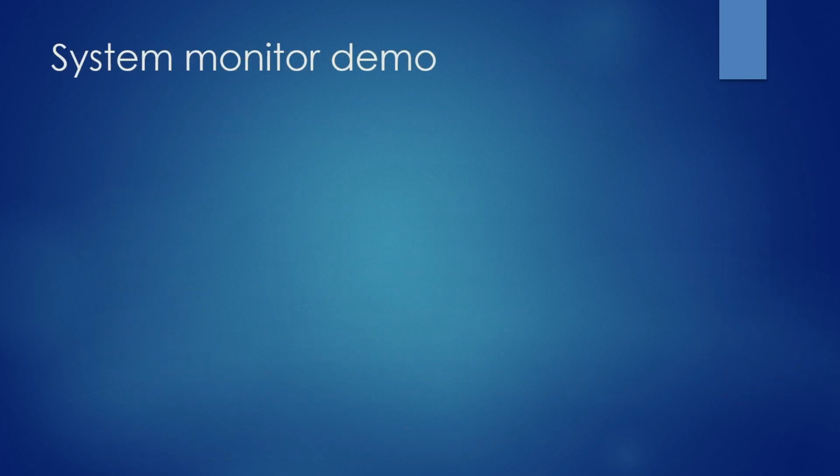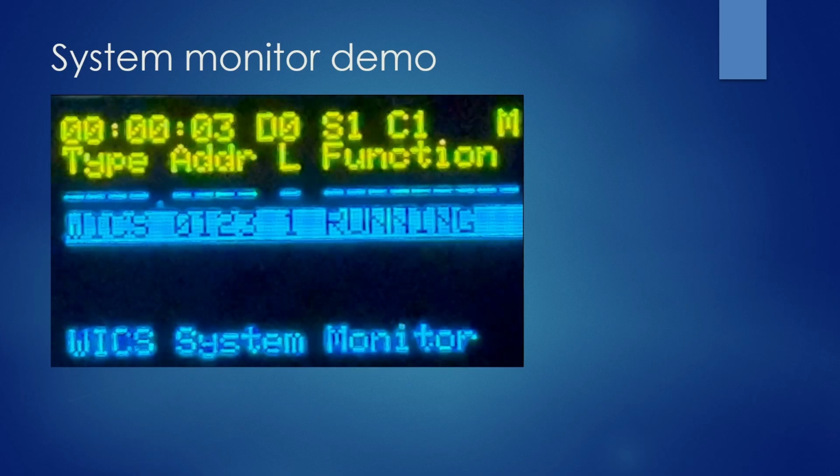Let's look at how the system monitor works. Remember that we have 3 time events. Every minute at second 0 and 30, address 109 is turning on and off the LED strip. Every second minute at second 5, address 115 is turning off the arc welder. Okay, let's start on day 0 at midnight.